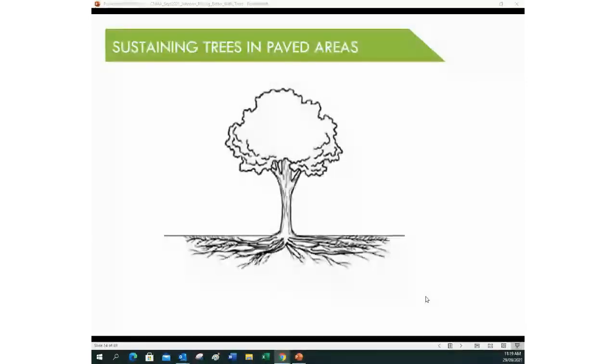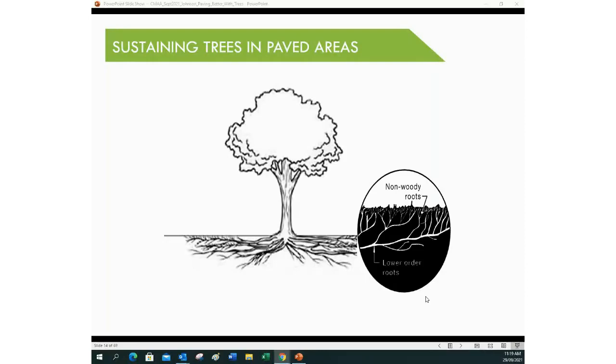What then happens, we come along in that natural woodland system, a greenfield development. We start to impact the roots. You can see there most tree roots grow up, contrary to popular belief. They need oxygen, they need water. The oxygen diffusion is through the surface, so most roots are near the surface, fairly shallow. They're seasonal in Australia. They grow up in autumn, winter, spring. When it dries out, they die off and grow down to where the water is, so they cycle annually.